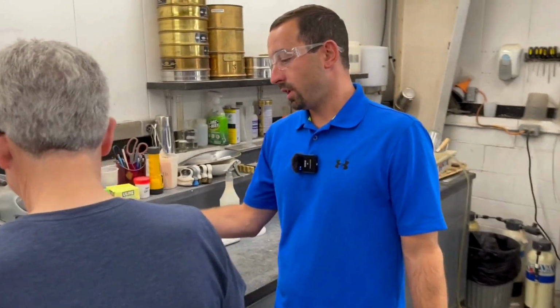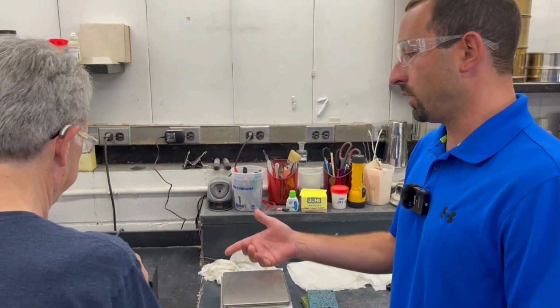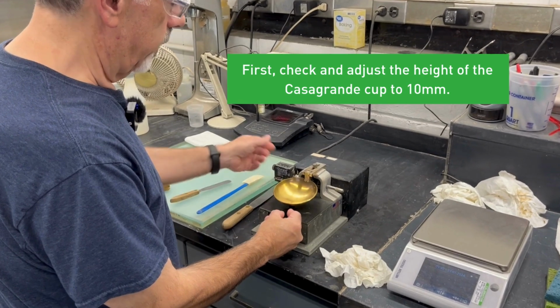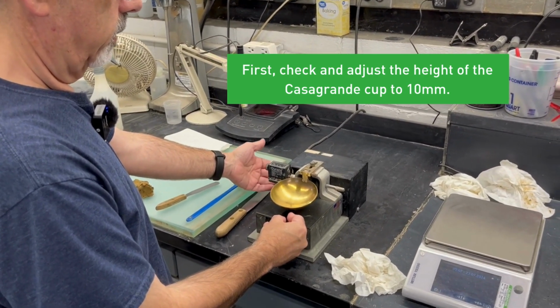So we got the Casagrande cup out and ready to do our liquid limit test. The first thing, Mary, you're going to do is what? We're going to check the height. Check the height, calibrate, and make sure the drop is from the right height, and the grooving tool on the back of it has the proper height.